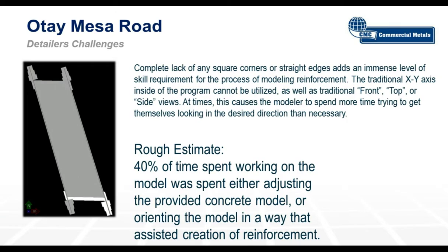So I asked my detailer, what are some of the challenges that you see with modeling rebar for bridges? And he was pretty honest about it. Complete lack of square corners, straight edges. Whenever you're modeling, you can't use the traditional XY axis and the front, top, and side views to reinforce the concrete members. You have to spend a lot of time rotating and orienting yourself around the model so you can reinforce it properly.